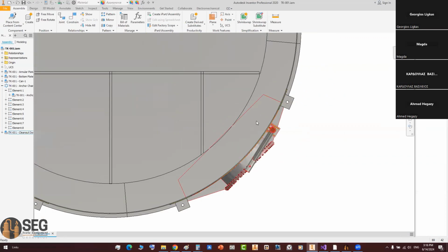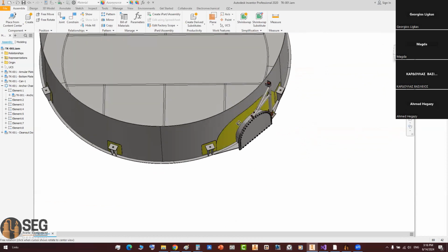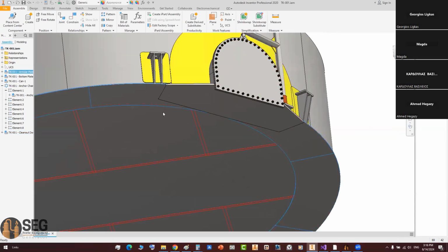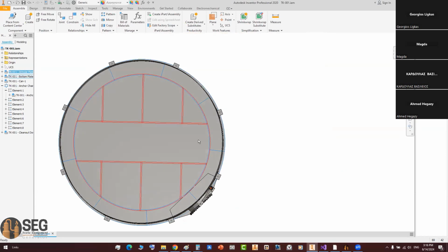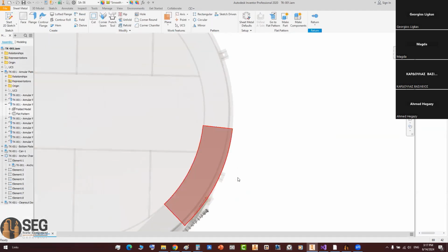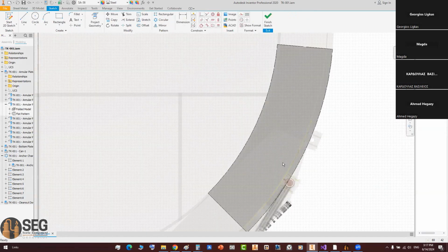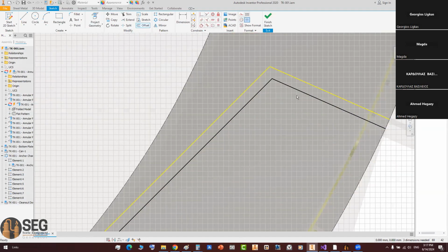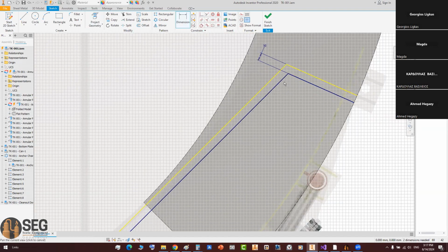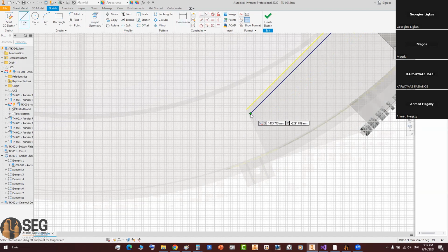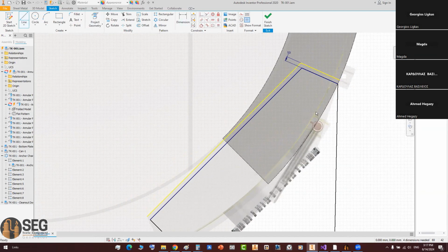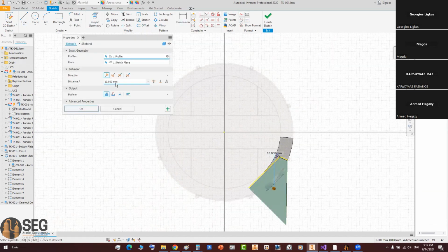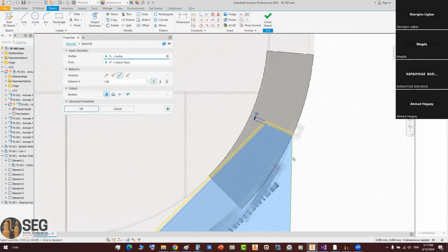Now as you can see here, we have this annular blade intersecting with two other annular blades, that one and that one. So now let's check the option of modifying the annular blades manually. Let's go inside this annular blade and make a sketch on this one, print the annular blade lines here, and make an offset of 35 millimeters or 50 millimeters, to make a cut inside this annular blade. We need to make a cut on this annular blade with all sides.